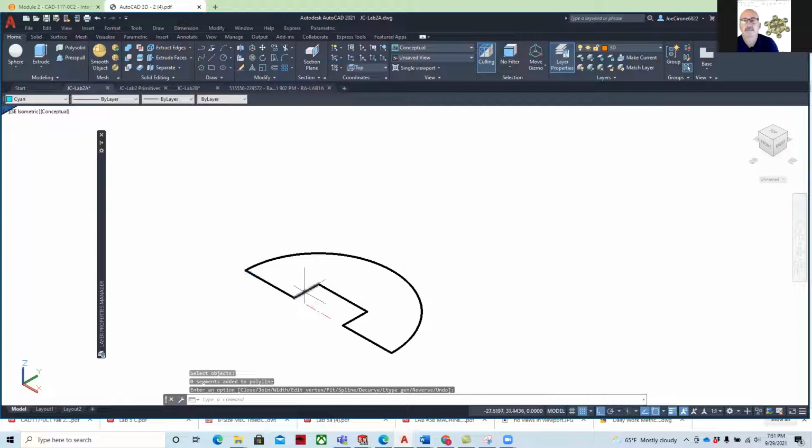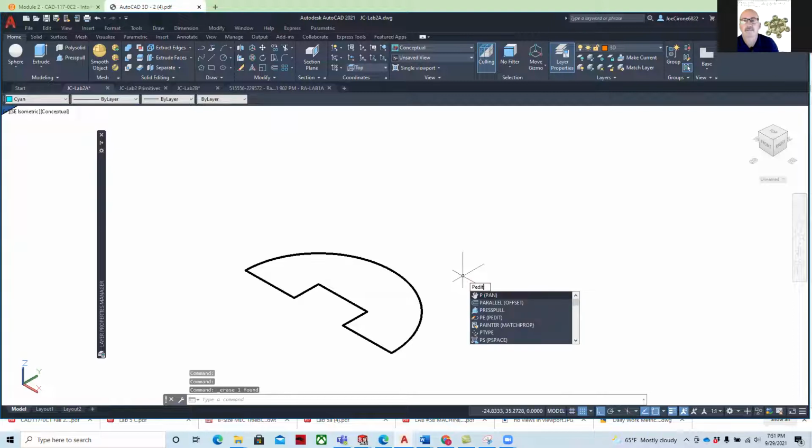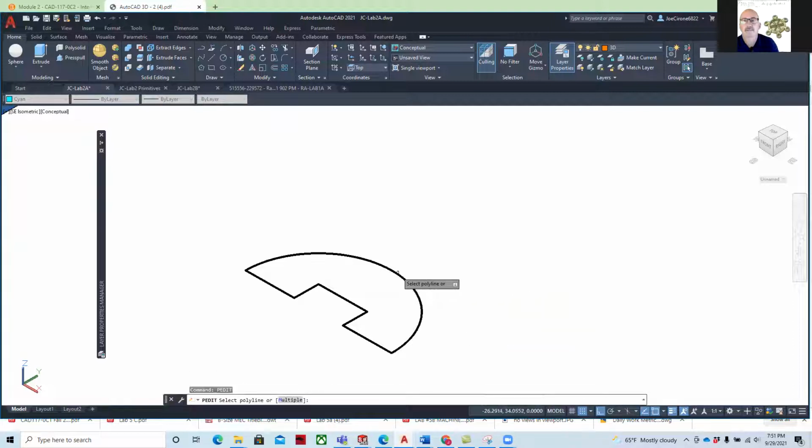Now it's a poly. Well, I thought it would be a polyline. Apparently it's not. Let me erase this out and let's try that again. P-edit. Select one of the lines. Join. Select all of the lines. Hit enter. Now there's an error with it because what it's finding is that 0 segments have been added to it.